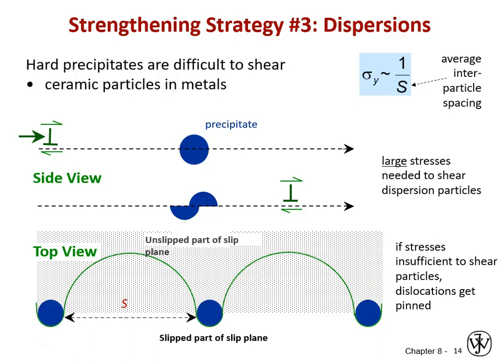And so the boundary between it and the parent material, the parent crystal lattice, will always be there in your service environment at your chosen temperature, if you pick the right one, for a dislocation to bump into. So if you have a dislocation moving along through a microstructure, which you can see in our top schematic side view, it's being pushed in the direction of the green arrow on the left. So we have a left to right shear stress. It's going to propagate from left to right.